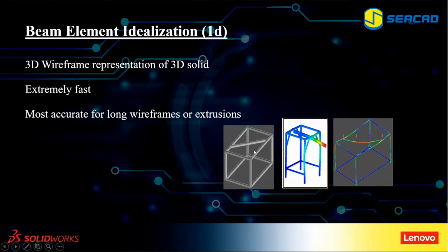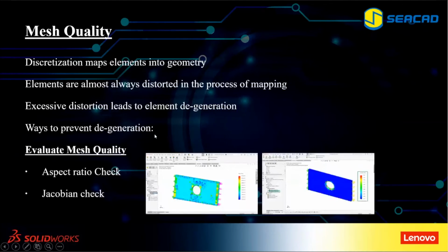Usually in SolidWorks, the beam element will be created for the weldment and the structural member. So remember, in what condition we should use the beam element in SolidWorks Simulation: for the structural member and the weldment. So this is the first topic in the webinar.